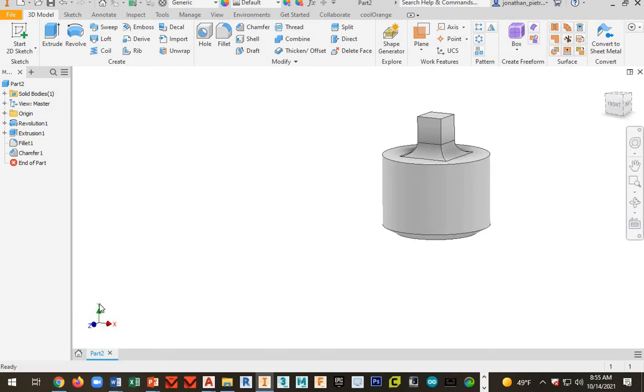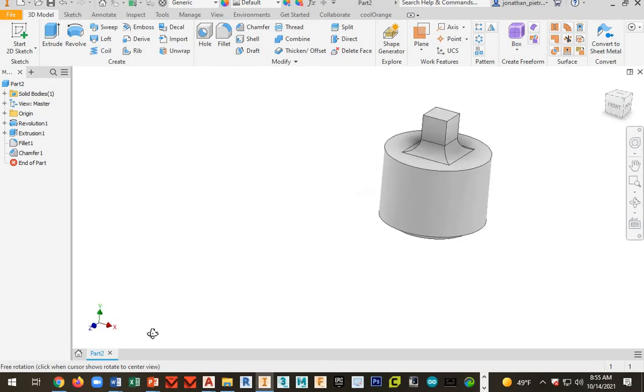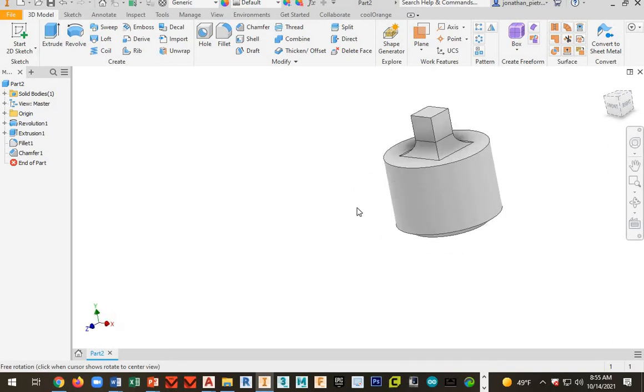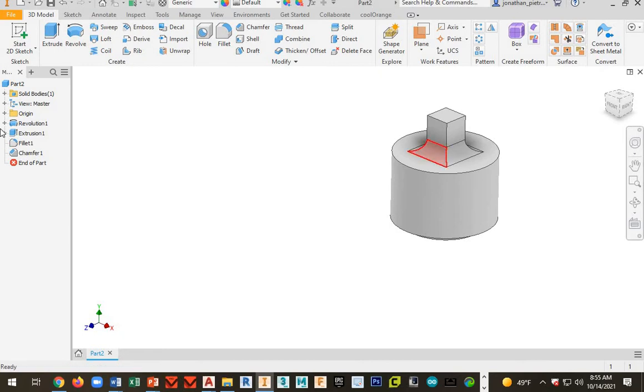you see down in the lower left hand corner of my working space, this is my user coordinate system, UCS, my XYZ coordinates. I want to make sure that the Z is pointing toward you, okay? So if you have to revolve around to get it that way, kind of important, otherwise your name will show up backwards. We don't want that.